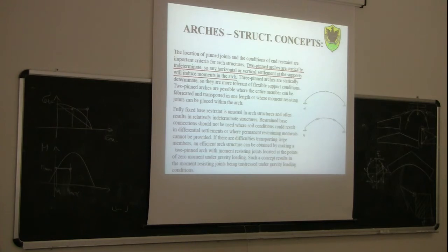Of course, the choice between 2-pin and 3-pin arch is based on some concepts that we already saw yesterday for the portal frames. 2-pin arches are statically indeterminate, so any horizontal or vertical support movement will induce moments in the arch. 3-pin arches are statically determinate, so they are more tolerant of flexible support conditions and also of possible differential settlements of the foundation.